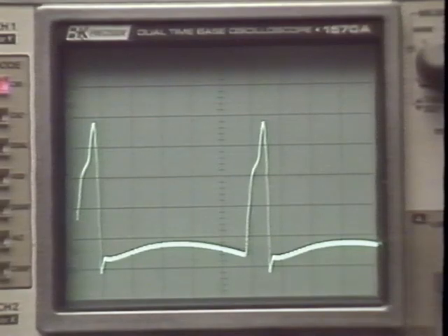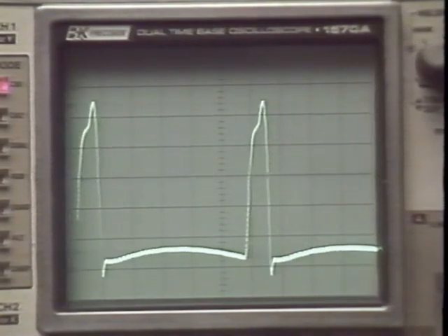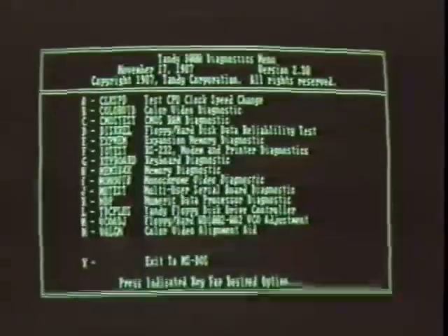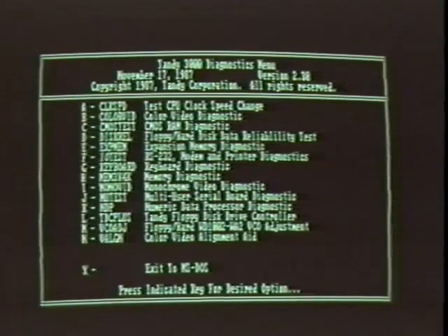Next, adjust the horizontal size, which aligns the oscillator's duty cycle. Make the linearity adjustment last, as it fine-tunes the oscillator output waveform. Once the horizontal adjustments are complete, move on to the vertical sweep circuit. When it is also correctly aligned, you will have a clear, stable display, which makes it much easier to perform the rest of the alignments.